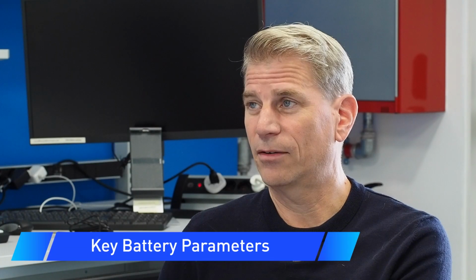How about as a battery ages, things change, right? So how does that get handled? So this is the state of health parameter that everyone knows, that it tracks the age. This state of health parameter tells you the degradation of your battery. You also provide this for every individual cell, which I think nobody else is doing, but as I told you, it's very important because you can know how good or bad your battery design is, or if you have to redesign it.